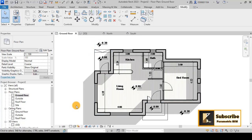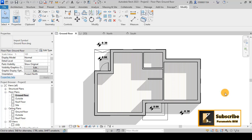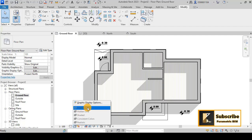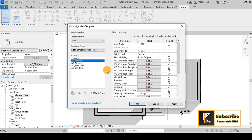Maybe, if you don't know this procedure and you have background and you haven't the opportunity to make it foreground, you can go here to the visual style and make it a wireframe. But it is closed because I have a view template here, and I will also teach you how you can do a view template for all floor plans, for example, or elevations or site plan.